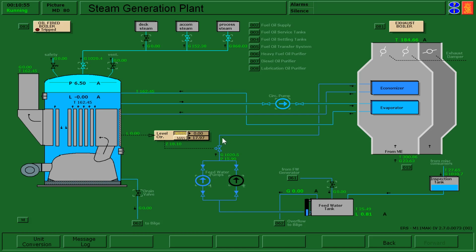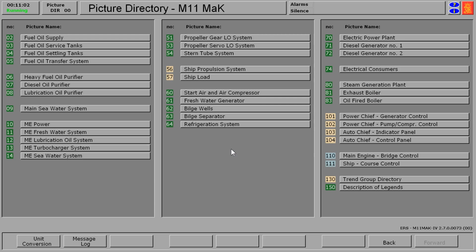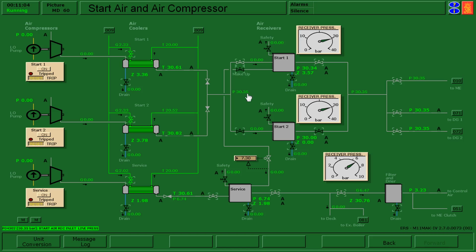So in order for us to be able to run this valve, what we need to be able to do is make sure that we have a functional compressed air plant so that we can control our control devices.